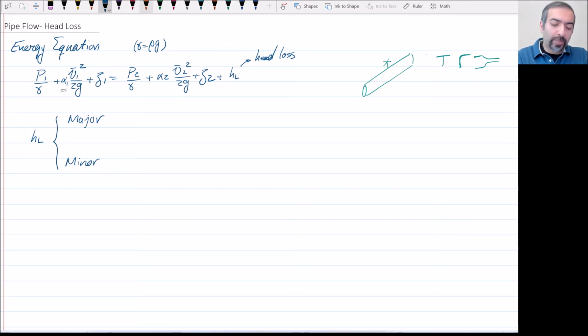So one interpretation of this term is: how much pressure drop or pressure difference do we need to achieve a certain volume flow rate? And then to make the dimensions work, we divide this by rho g. So this is the delta P due to viscosity, the delta P that we need just because the fluid has viscosity. This pressure, delta P, is going to be 0 if viscosity is 0.